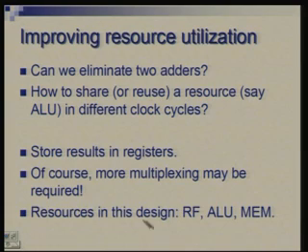So, you do something, store the result, and then the resource adder in this case is free to do the next operation. So, same idea we will apply here, and the 3 key resources we will keep in mind is register file, ALU, which will do all arithmetic and logical operations now, and the 2 memories will be clubbed into a single memory. It will store program as well as data.